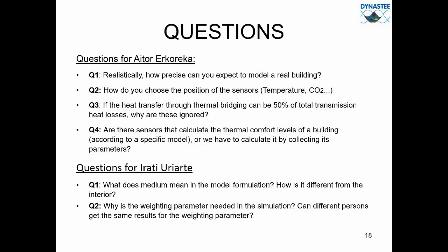You install the volumetric flow meter in the return, and then you install a temperature sensor in the water inlet, and another temperature sensor in the return. Then you make a conversion of the volumetric flow rates to mass flow rates, and you have mass flow rate multiplied by the specific heat of that fluid. Usually it's water, or water with some glycol or some type of fluid, so as not to get frozen in case there are tubes in the exterior. And you get from the manufacturer how to install it.